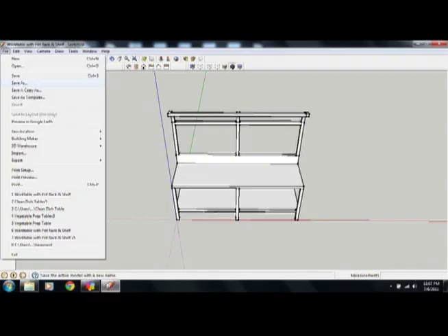When creating the SketchUp model, it is important to use the red and green axis as the base of the component, because this axis will be used to determine the base of the component when it is placed in a Revit model. Keep in mind that you should only model simple components in SketchUp. Revit will not display complex models correctly. Also, none of the finishes added to the component will transfer to your Revit model.